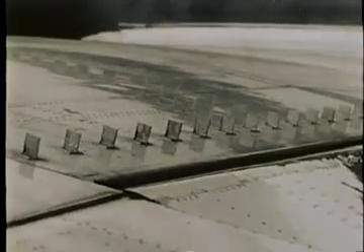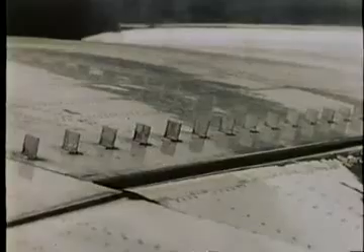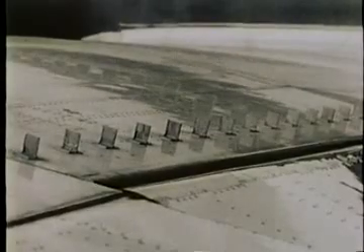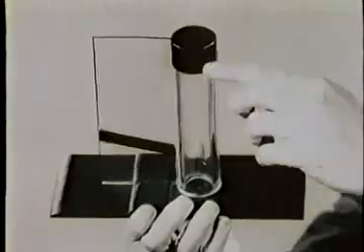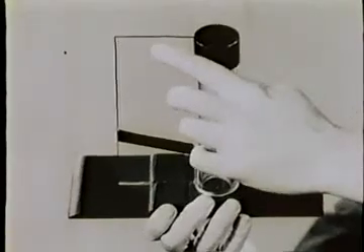In this film, we looked at flow along a flat plate and then saw the effect of pressure gradients on boundary layer flow. Now we can understand how this cylinder influences the flow on this plate. Without the plate attached, there is a static pressure increase along the stagnation streamline, with a corresponding decrease in velocity.